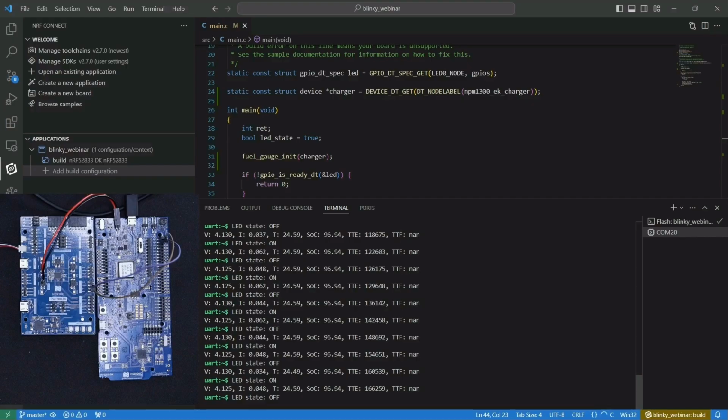So there is obviously a hardware component to this, which is a PMIC. A PMIC is something you would typically need in your application anyway, so you're sort of getting the hardware part of this for free. And then the demo is focusing on the software component of this fuel gauging method, which is the same for any Zephyr RTOS-based application. And that is why we have named this webinar that. It is because it will be possible to implement this in software in any Zephyr RTOS application, as long as it's running on a compatible ARM Cortex-M4 or M33 core.